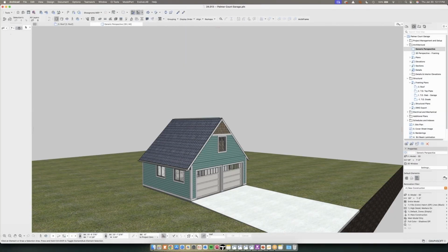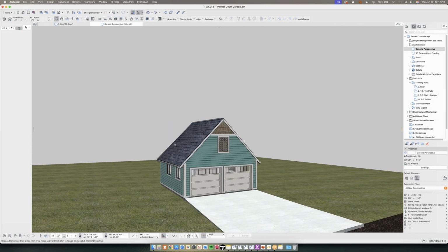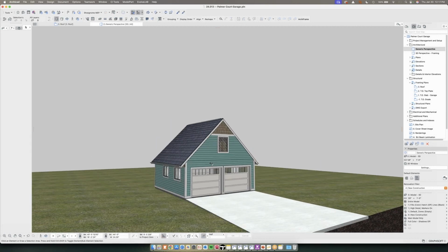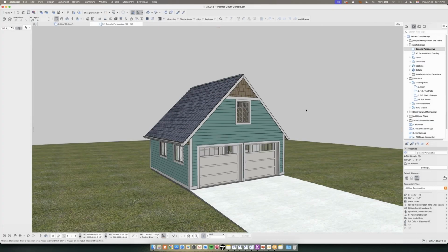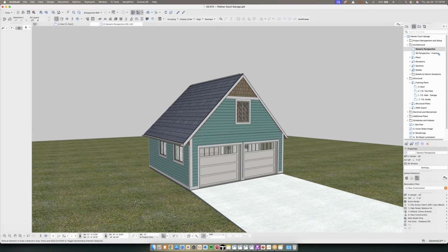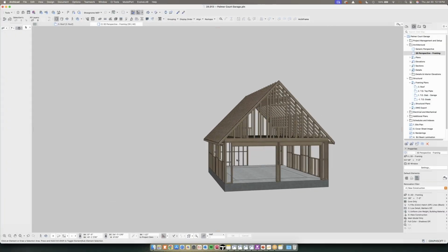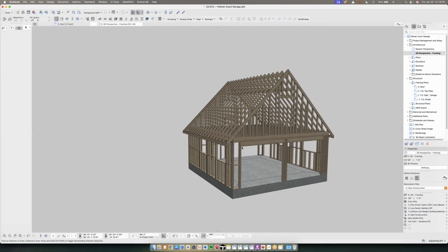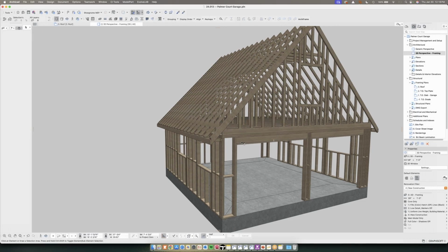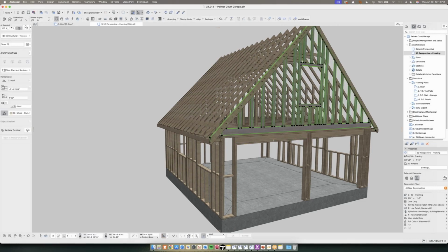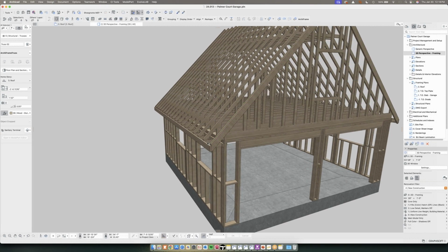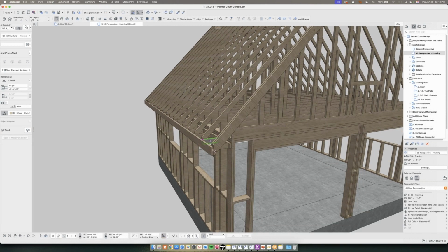This is just a simple 22-foot by 22-foot garage that was done for some customers local to me here. They're actually friends of mine, but just to see the level of detail that gets put into this. This is the generic 3D model that most people would see, but then simply by creating a layer property, we can turn that model into a complete wood frame structure with individual components for lintels, trusses, outlooker framing, sub fascias, nailers for soffit.